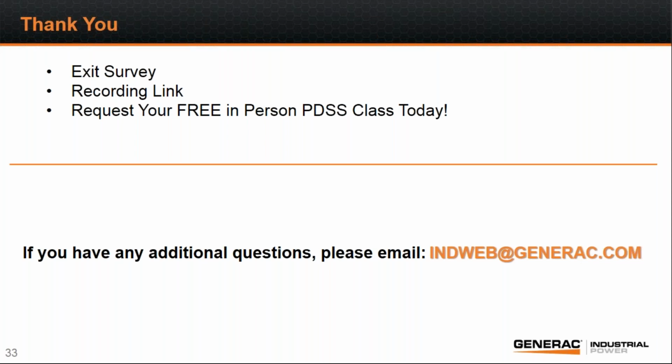So it isn't as straightforward as defining a specific voltage dip, because what happens is those standards actually say you get to derate what you're calling your input transient based on the BMEP of the engine. So unless you're really familiar with that standard, I would not hold my hat and say I spec G3 and that somehow is going to mean something to the market.